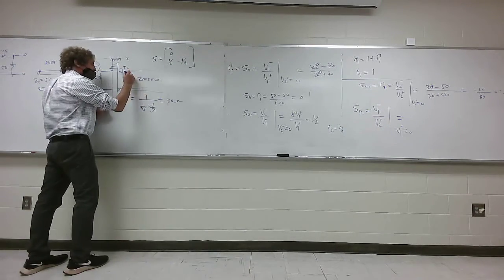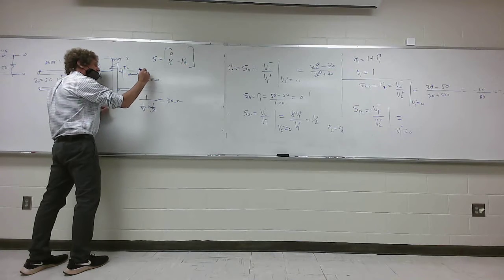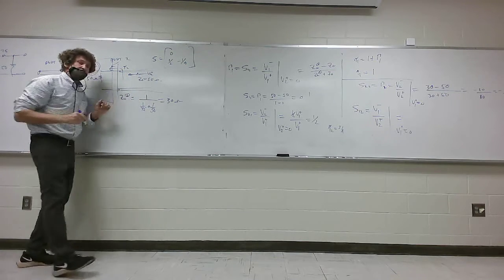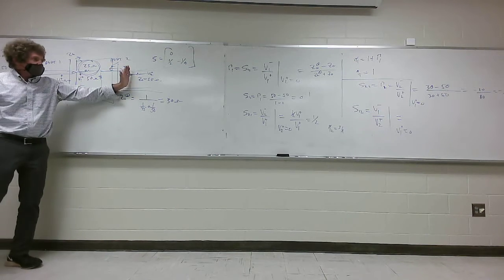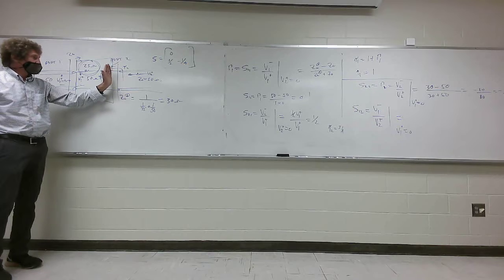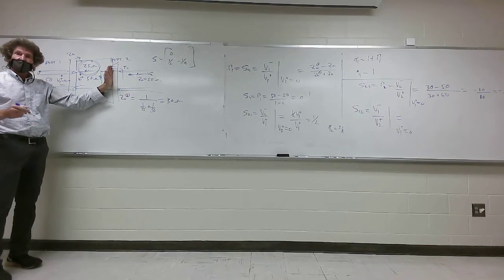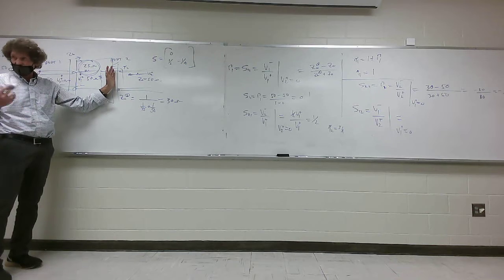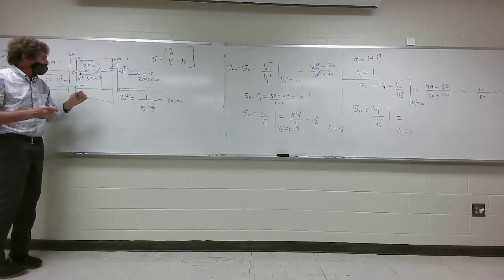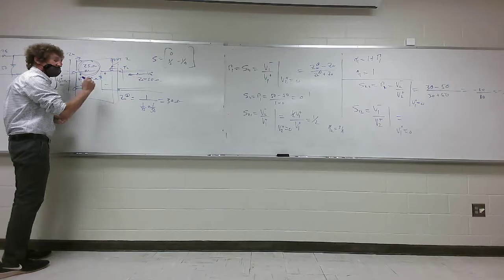So if I have a voltage waveform coming in here, and it's V2 plus. Now I want you to watch this. Believe it or not, this is one of the things that people, I think, are just casual about, and they blow this left and right on exams. So I got that coming in, V2 plus coming in. Then I have to multiply it by the transmission coefficient, tau 2, to get this voltage, which is right here. You all see that?